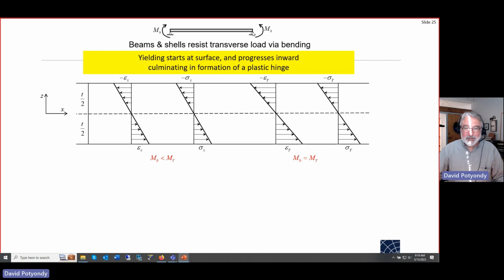There'll be no shear stresses. This is called pure bending. If we then look at, this is the thickness of that beam. So the thickness is in the up and down direction here, right? So here's the applied strain. It gets shorter on the top and it gets longer on the bottom, which then corresponds to the stress. It gets a compressive stress on the outer fiber top, a tensile stress on the outer fiber bottom,